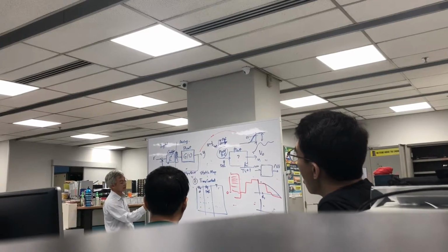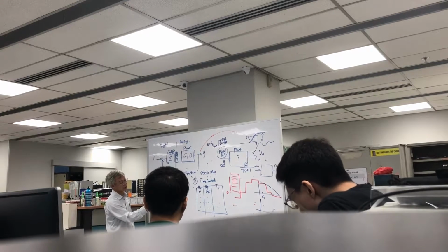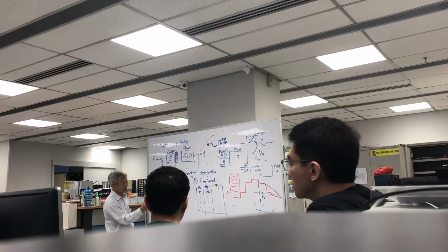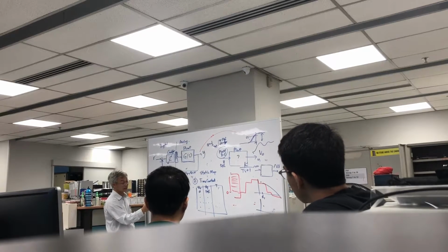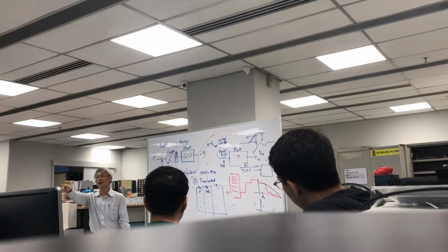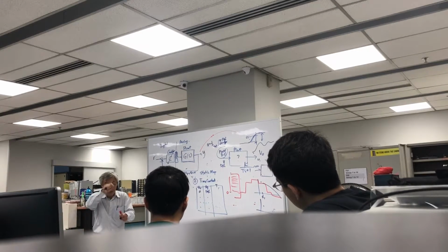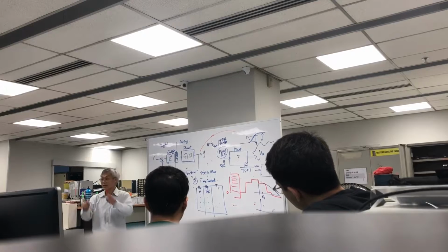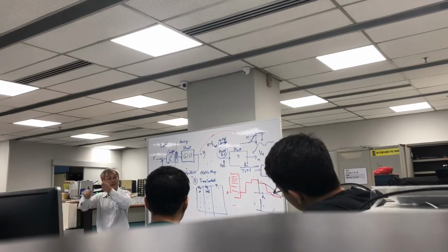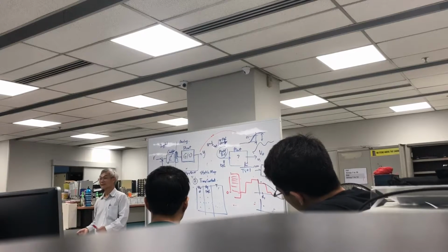You set 10% duty cycle, and then just delay and let it run. Then you look at the monitor, oh, this number, record, you got a point. Then you go to the program, set 20%. Oh, this number, record this point.